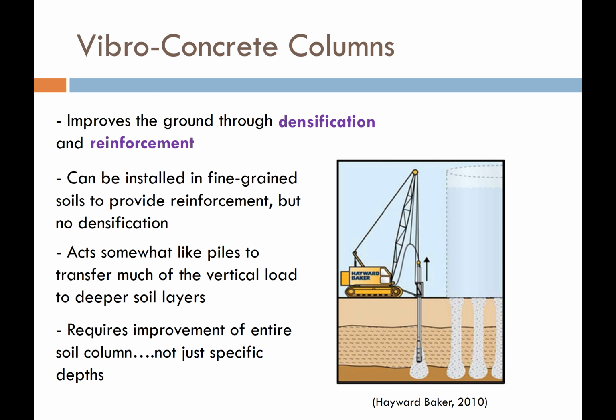It depends on what your soils are like down in the deeper layers, and then you need to make sure that you design the concrete columns to be able to work like that. Like before, this method requires improvement of the entire soil column, not just a specific targeted depth.